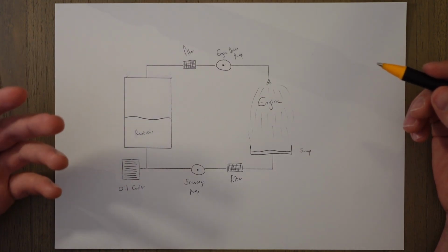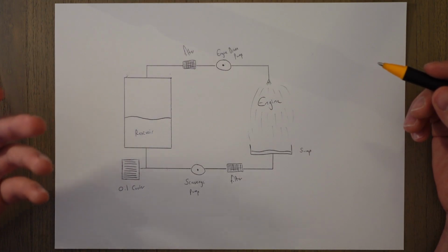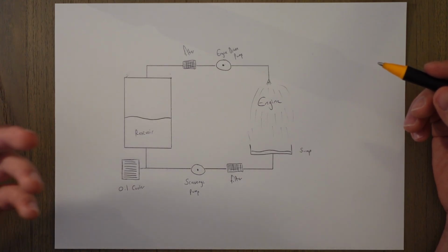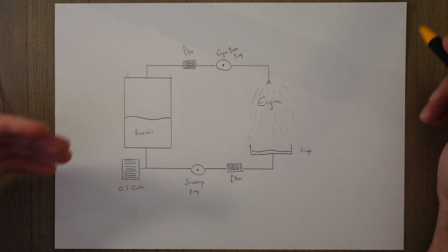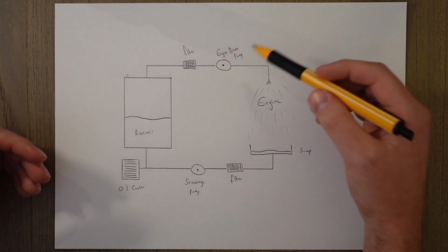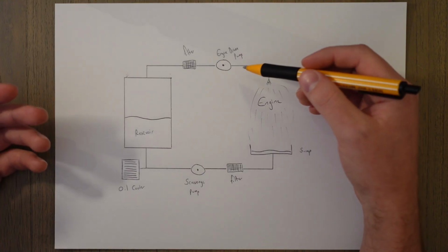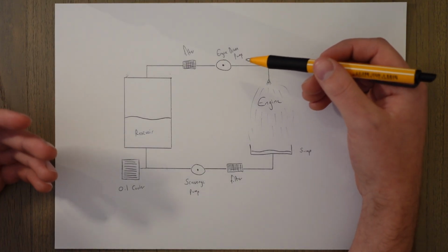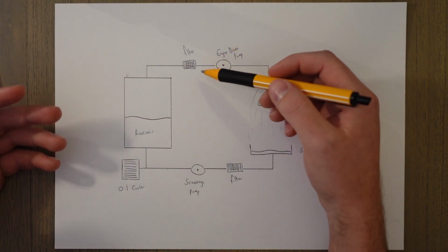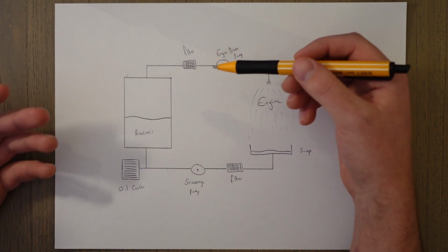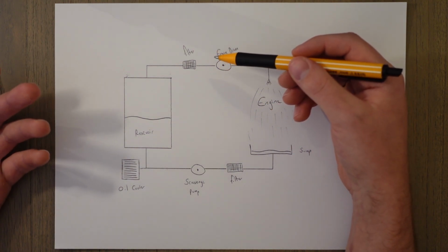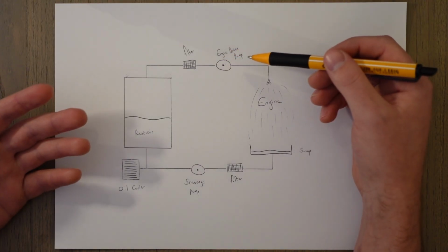Generally speaking, there are two types of oil system. You've got dry sump and wet sump. In a dry sump system, which is what this is, the oil is drawn from a tank by an engine-driven pump. The pump will have a variable output pressure depending on the engine RPM. The pump will also have a filter just before it to remove any of the small metal particles or other contaminants in the oil that could break the pump.